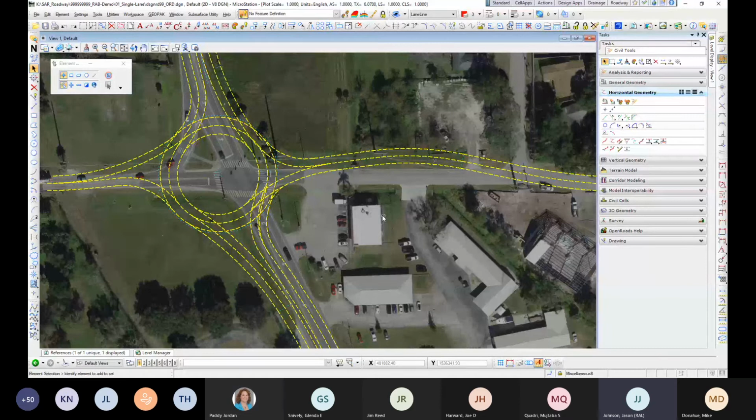Have you ever just basically laid out the center island area with the truck apron and everything, and then used a terrain for the pavement based on a linear template for the outer curb and gutter as it runs around the intersection? That's almost exactly what I do.